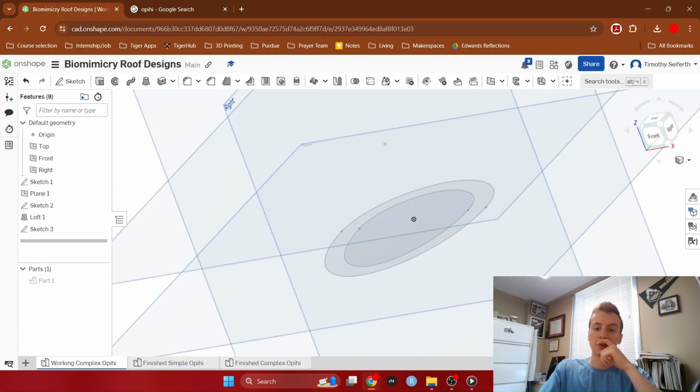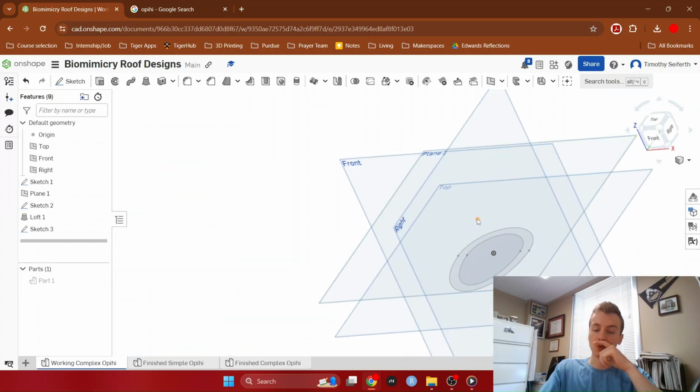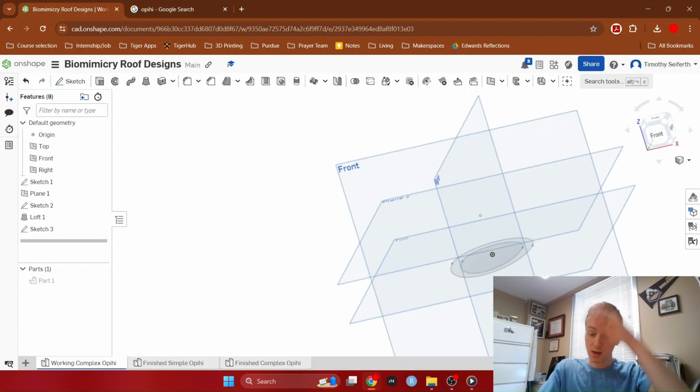And then again, we need another plane for our point that we will make this cone with. And we don't want it to be right at the top, or else our cone would get incredibly thin at the top. So we want it to be 1/4 of an inch thick even at the top. So we need a second plane.